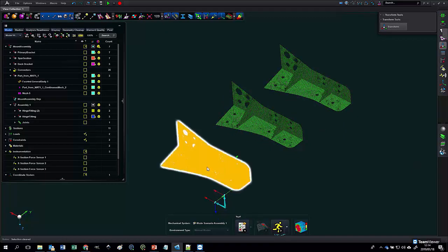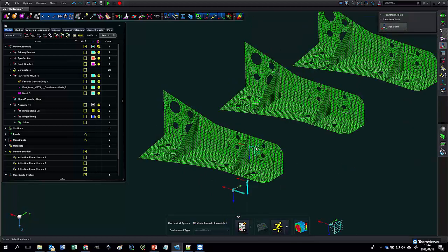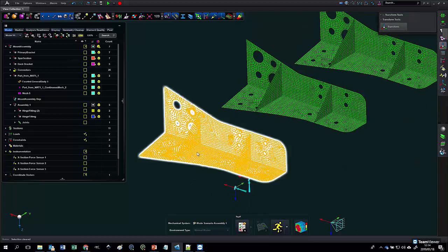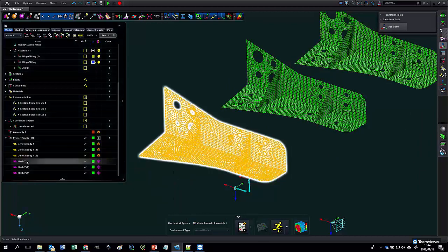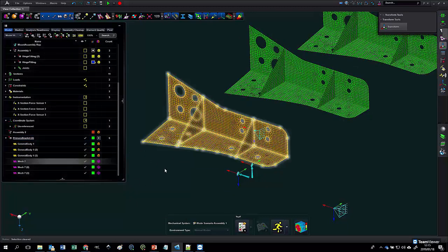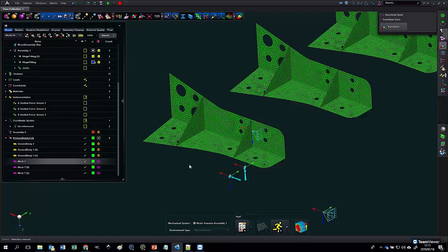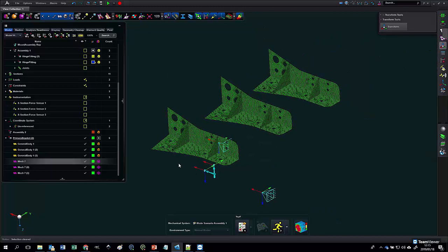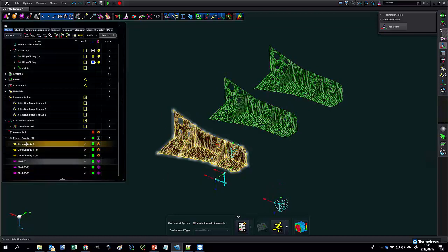Why do we have stitched versions? Well, that's the typical traditional way of dealing with bodies. The problem with stitched bodies is that they can only be in a single part. We can't have multiple surfaces from various parts stitched. If you want to have them in different parts, we need to use either glue or edge ties. Okay, at least we have all the options.